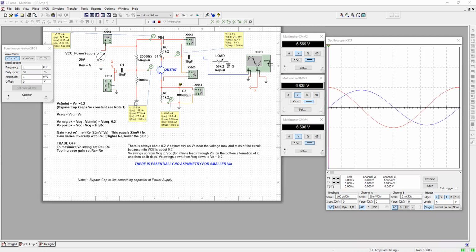The transistor by itself, without any impact from the capacitors, will put a 180-degree phase shift on its input, simply because of KVL and Ohm's law. Your increase in current will reduce your voltage at the transistor's collector.